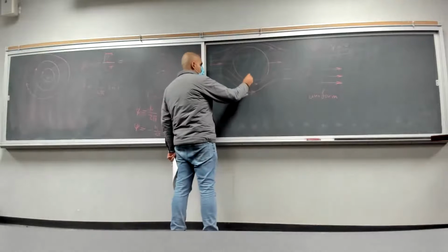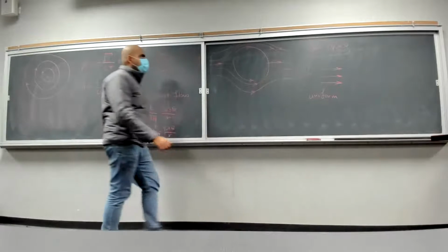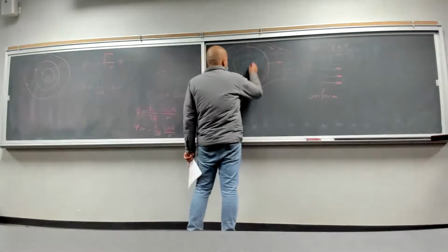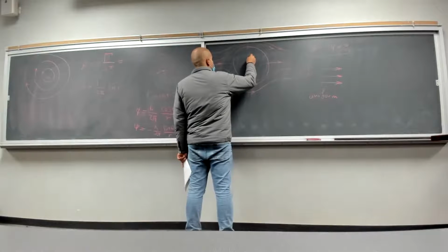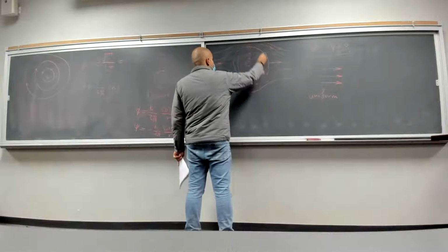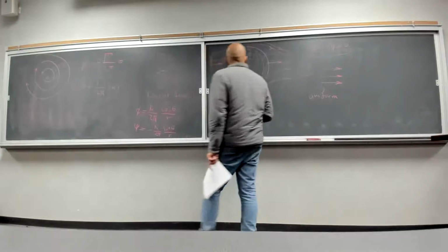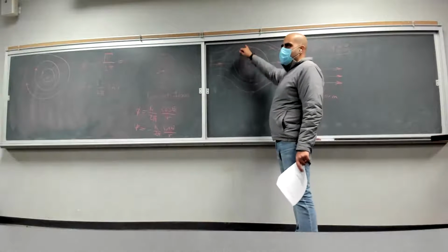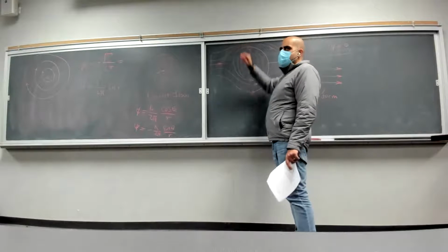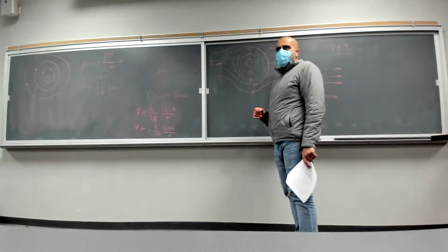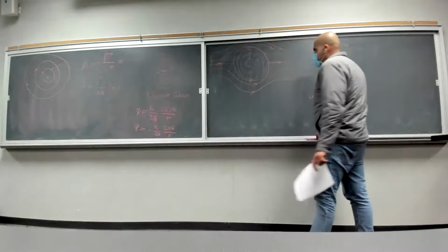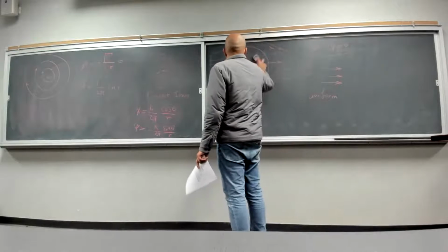The idea was, the velocity here and here for a flow past the cylinder are the same, right? We are going to have the same velocities. If we have the vortex flow, and with the center of vortex here, we are not going to get the same velocities on top and bottom, because on the bottom, you're adding these two velocity vectors. On the top, you are subtracting, right? So it cannot be vortex flow. But what do you think? What is it then? If not vortex flow, which flow?